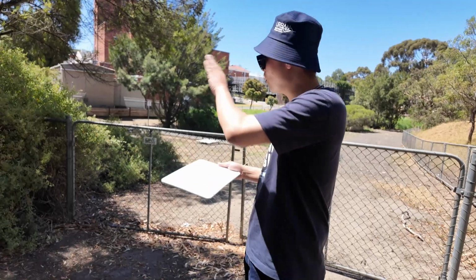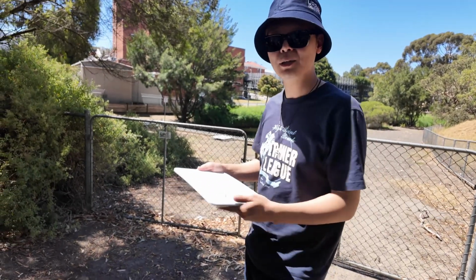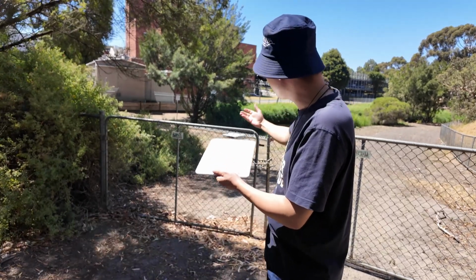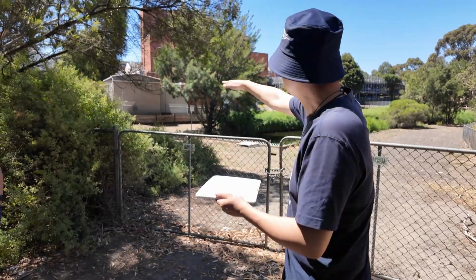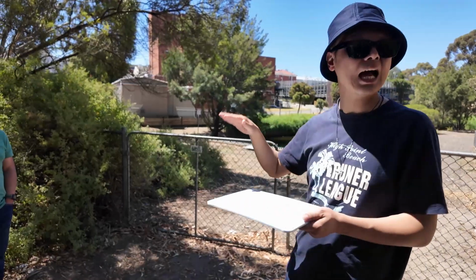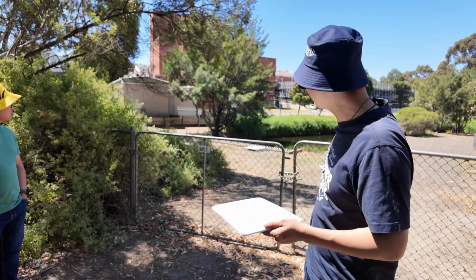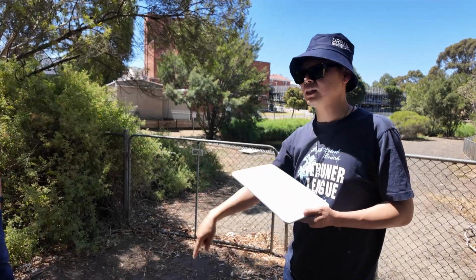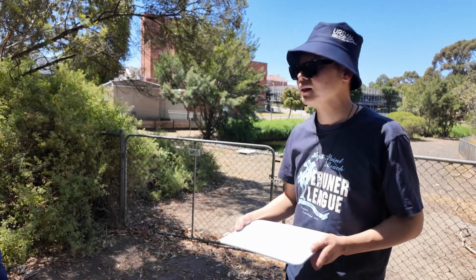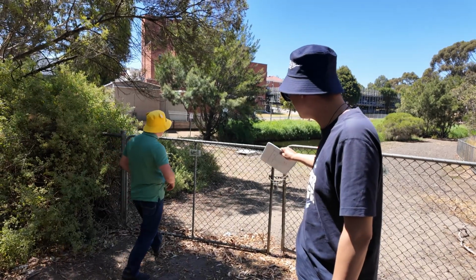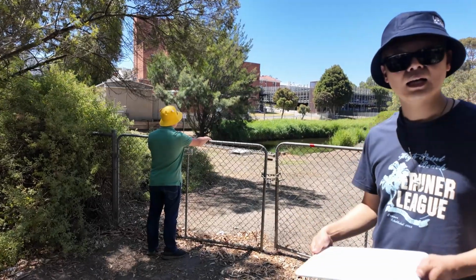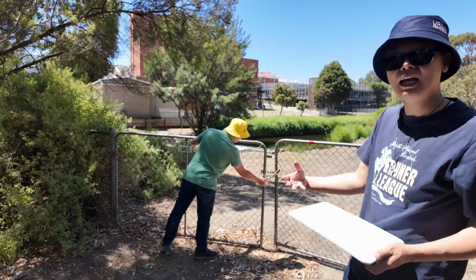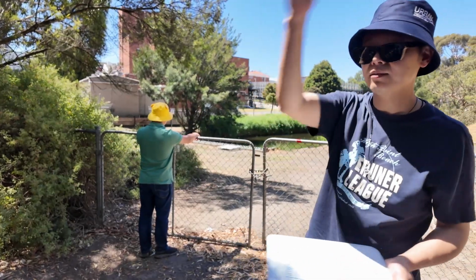So that's why when we walk you to the wetland, you see no sediment basin, because this is the sediment basin. So there's a lower pipe that takes water to the wetland, and this whole weir serves as a high flow bypass. Right? So when the flow is really high, it goes straight into this overflow weir and goes to a deep pipe that connects to the downstream. Again, you see every sediment basin needs to be designed with a ramp, so trucks and diggers can go in and dredge the sediment every 5 years, theoretically every 5 years, and ship it somewhere else.